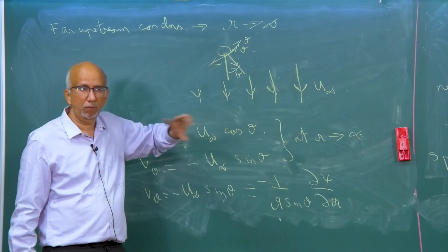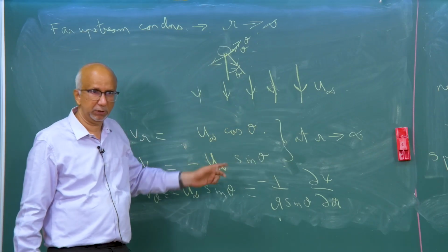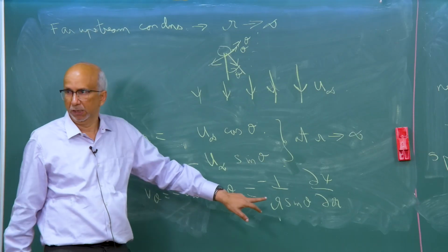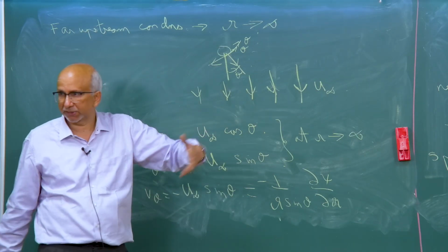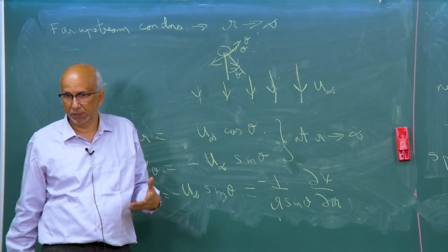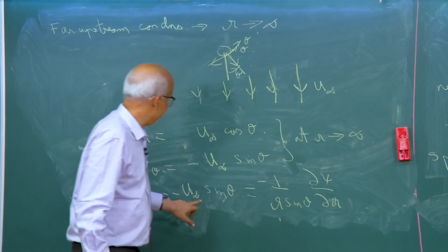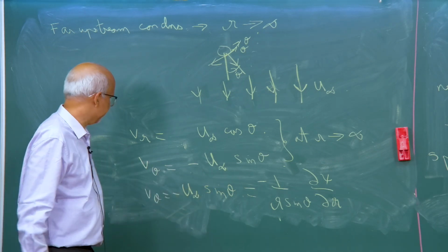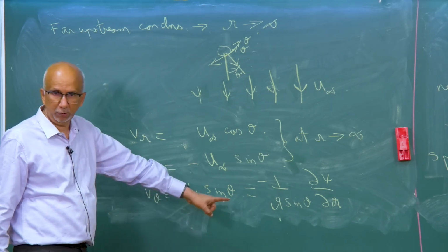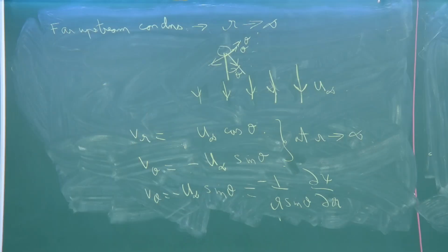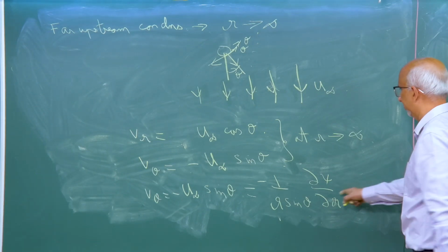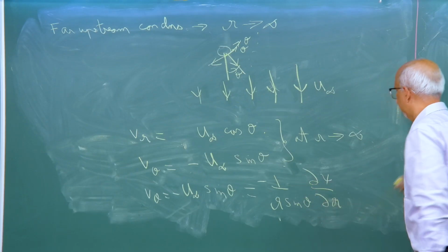What is the objective here? The objective is to convert this boundary condition to psi, because I am solving for psi in the stream function vorticity formulation. I want to get the boundary condition on psi. So I am going to set these two to be equal and calculate psi. You can just integrate this equation, the third and the second term.